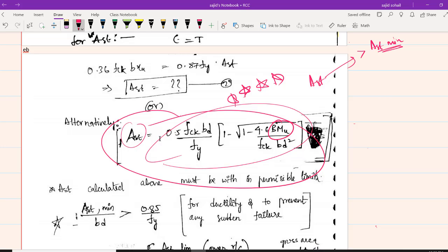See, I have designed a lot of houses. I have designed hundreds, thousands of beams. In most beams, if you are going for ground floor or G+1 construction, even if you provide AST as 200 mm square, it will be more than enough. Even 150, 160 satisfies. On STAAD.Pro you will get steel as less as 150, 160. Even one bar of 16 mm is enough to satisfy the steel requirement. But you will not keep so little; you will keep a minimum of 2-3 bars.